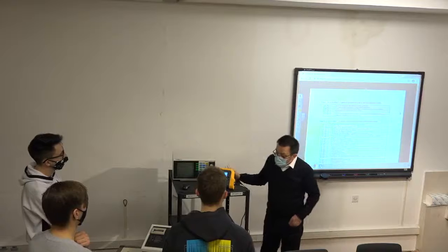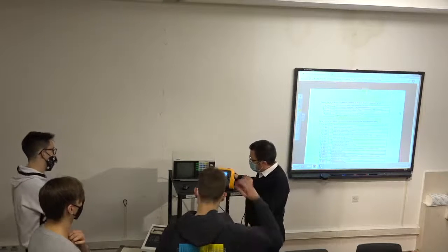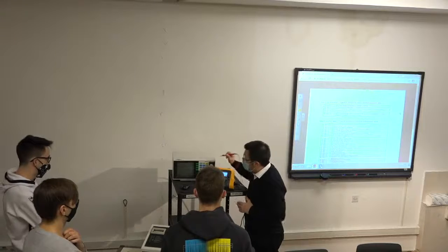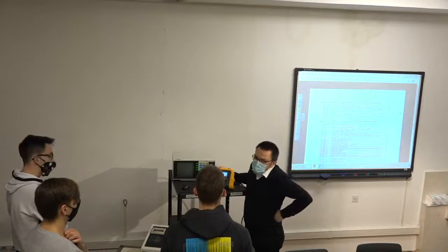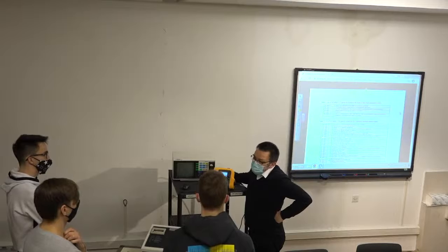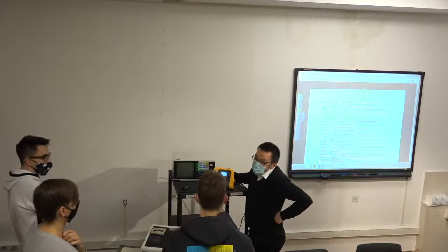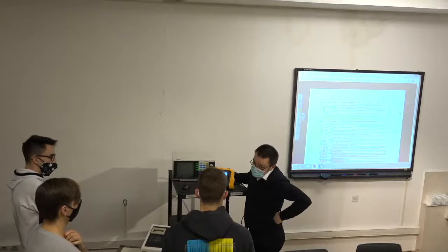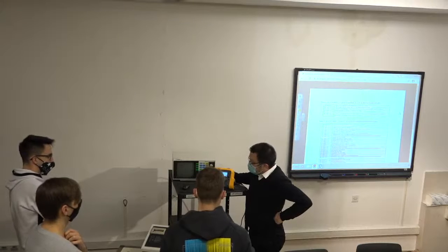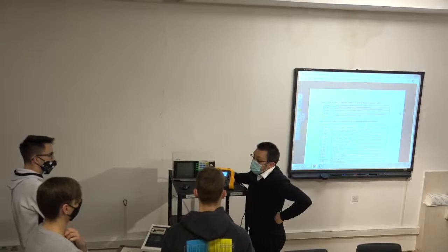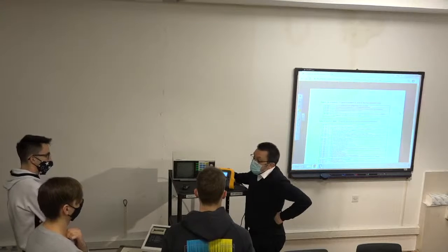So anyway, the idea of the whole testing is to go and check every one of the points where you have a real contact, so to see actually the voltages, the leakage currents, and the resistances. It's not a very funny job to do, but because of the safety of the patients, it's necessary.